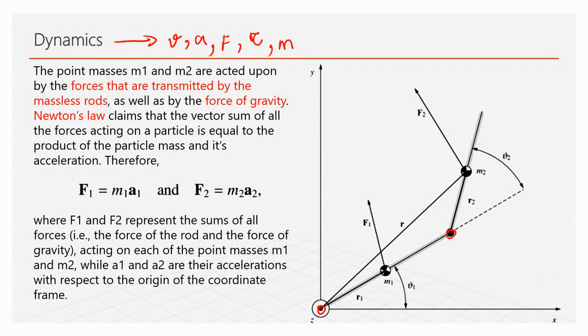The simplified model: we consider a point mass, a mass which is concentrated in one point, in a location in the middle of each link, with link 1 mass located at the center of link 1 with total value of m1, and mass for the second link is concentrated in the center of the link with total mass m2.